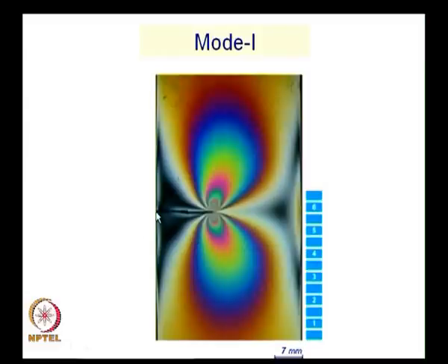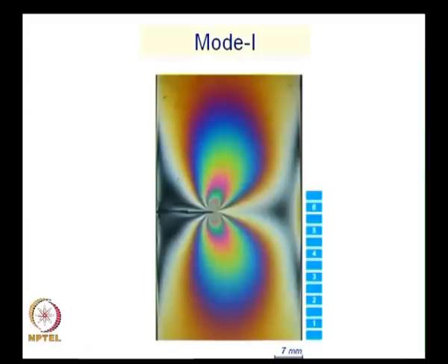If you look at here, you see the boundary of the specimen, and I have a crack coming from one of the edges, and this is known as a single edge notched specimen. I have a crack from this edge, I have the other edge shown here, and the crack is somewhere in the middle or slightly less than the middle. So, the a by W ratio would be something around 0.4, it is not 0.5. And you could also have a situation where the crack length becomes longer and longer, and the crack becomes closer to the free boundary.